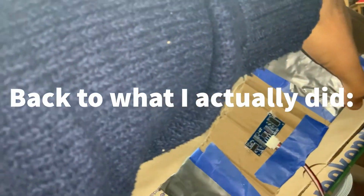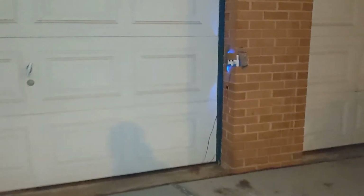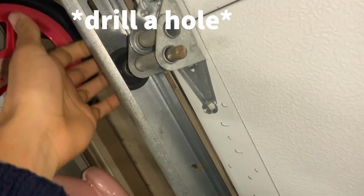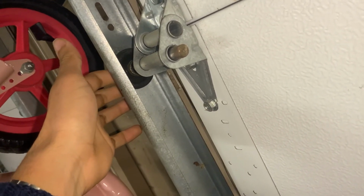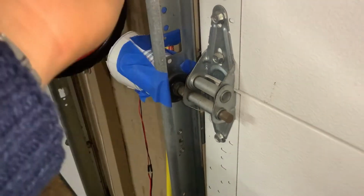I'm using the HC-SR04 ultrasonic sensor to detect proximity. It's got 4 pins: a trigger pin, an echo pin, power and ground. Every garage door has slots that the garage door slides up and down. If I drill a hole behind where one of these guide wheels is and place a photoresistor there, the photoresistor value will be high when the guide wheel is not over it, and it'll be low when the garage door is closed and a guide wheel is covering it.